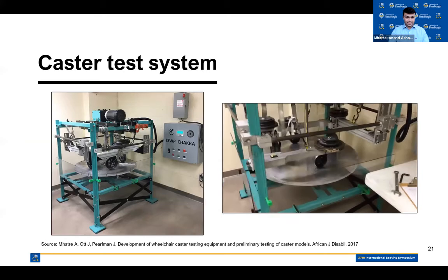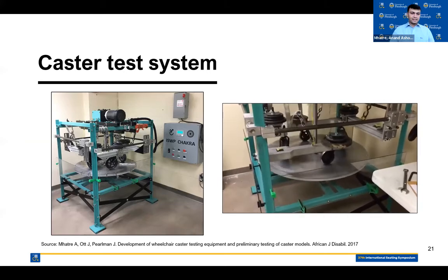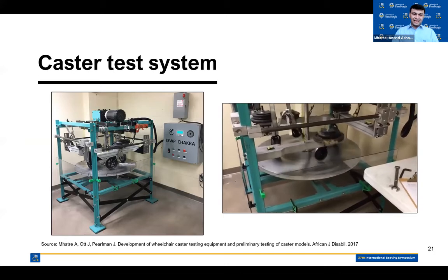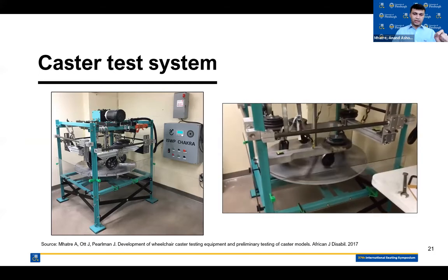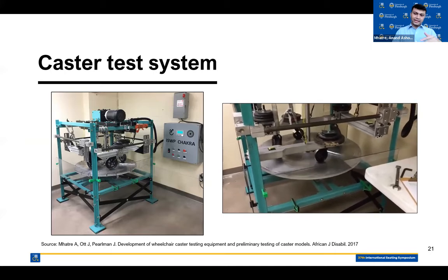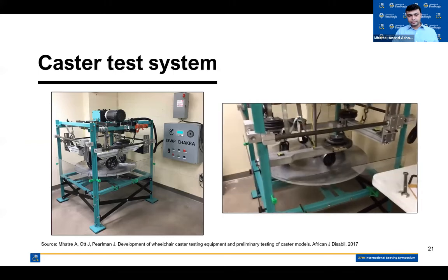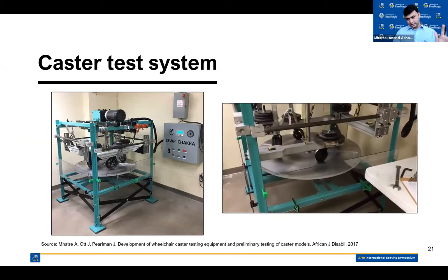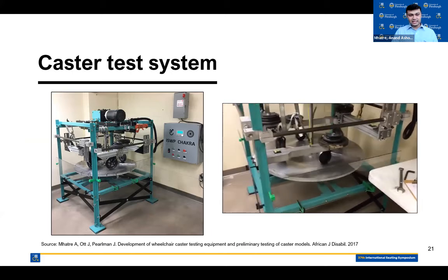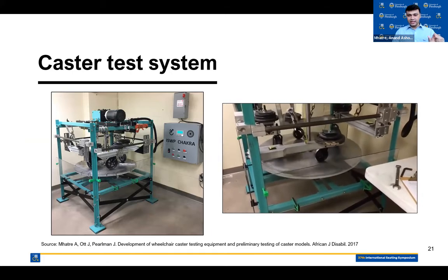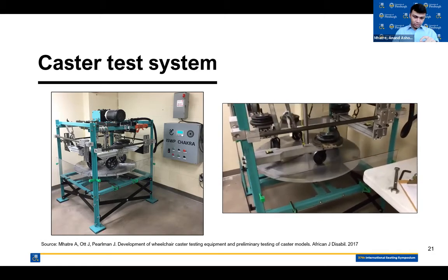Now, what is this test system? It essentially is a giant record disc player that has a couple of obstacles on it with standard heights, 1/2 inch, and it has casters that are mounted from an arm under a known load. And so these casters are hitting these obstacles and they are getting tested. With this validated test system, there is a lot of experimentation behind this, but these obstacles are standard heights, and I wanted to know how I can replicate the community shock profile on this one.